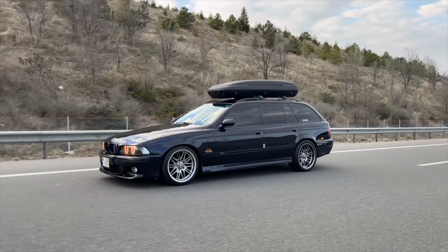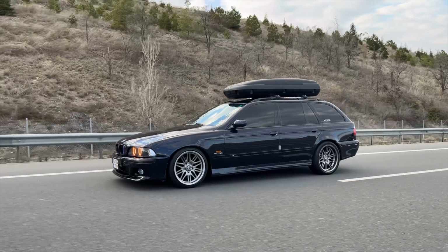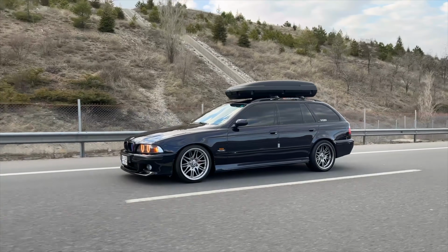Aliasing is like when you've seen a wheel turning on a car or a bike and it looks like it's going backwards. And this is the camera. It can't capture the true motion, so it folds it back into these false patterns where it looks like it's going backwards. In audio, when you drive digital saturation without enough resolution, i.e. a high enough sample rate, high-frequency harmonics fold back into the audible range as these nasty, non-musical, metallic-sounding tones.